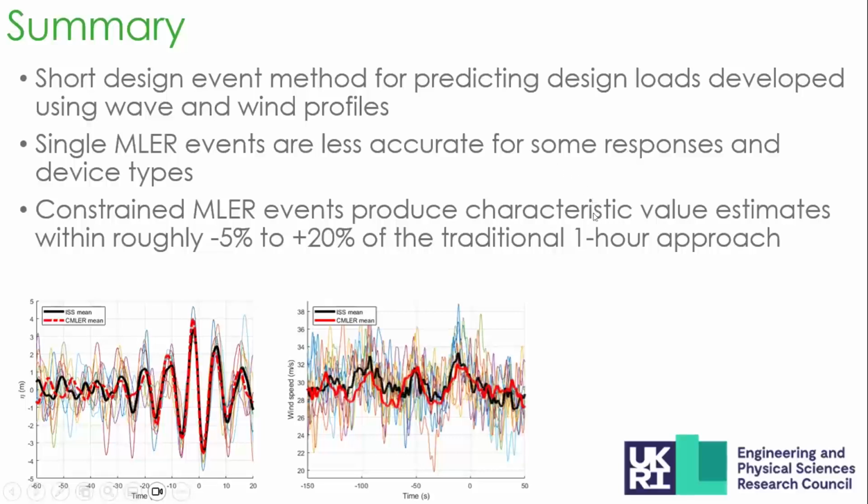For future work, we're in talks with DNV on what the success criteria should be for a method like this. So whether or not it can be included into recommended practice and design standard documents as it is, or whether more refinements are needed. We've also started to look at other cases. This was just design load case 6.1, where the turbine is parked in idling conditions. We've also looked at some cases where the turbine is operating.